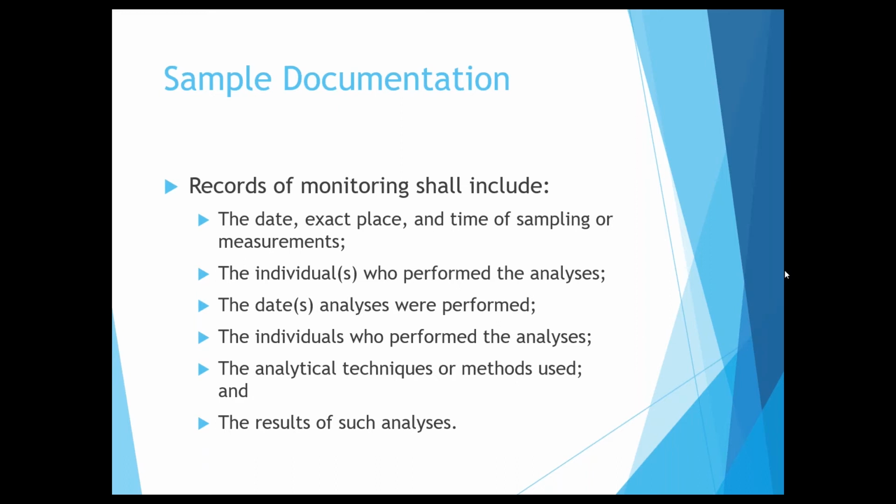You can always collect a process control sample. That way you have an idea of how your plant is performing and get better representation. But your permit writer wanted a 4-hour sample for a reason. So talk to your permit writer to make sure you're meeting what their needs are.